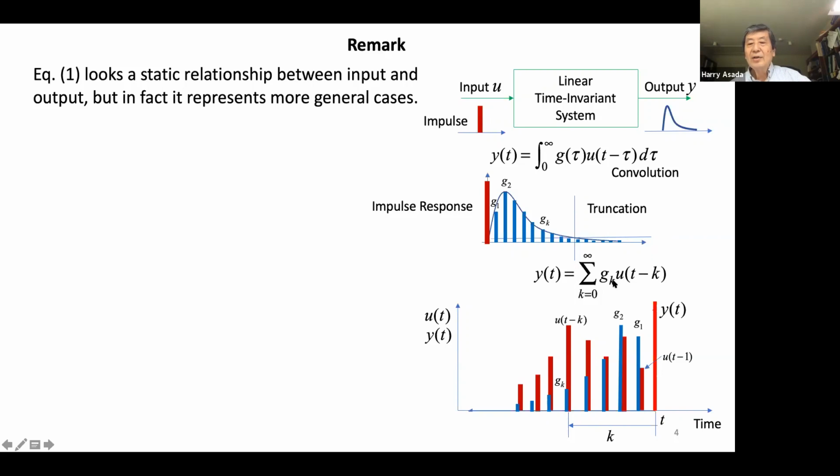Now, I think you can recall the convolution, but the physical sense of this is that suppose we like to see the output y(t) at time t, and this system is driven by some time function u, a time series input coming into this system, not just a single impulse, but a series of impulses coming to this system.